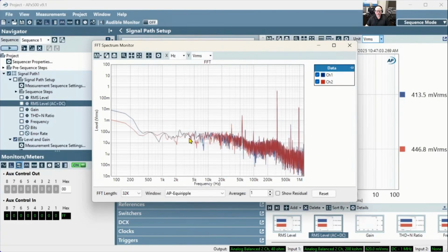What you can observe is up here to about 20K, you don't see anything, everything looks fine. But we have a bunch of stuff from the switching frequency of the amplifier, which is actually quite high in amplitude. Here at about 300K, we've got about 500 millivolts, 400 millivolts actually, you can see it right here, from the switching fundamental.